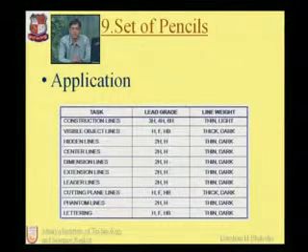The task consists of, the first one, the construction line. The construction line is drawn with lead grades of 3H, 4H and 6H, which is light and thin, meaning it is a thin line and its shade is light. The second one is the visible object lines, meaning lines which should be visible. For these, lead grades H, F and HB are used, which are thick and dark.